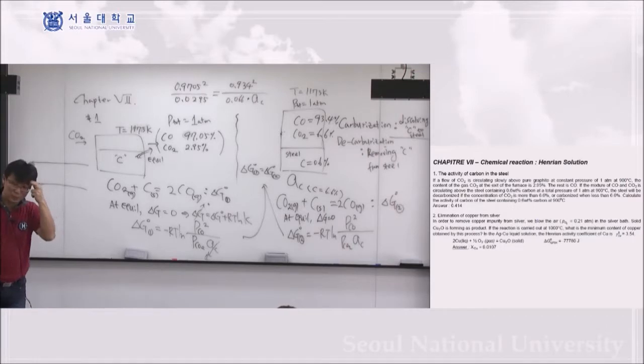The most famous use of this kind of technique is the blade. If you have a blade, typically one side is very ductile and the other side is very, very hard. When you have a knife, the edge you use to cut is very hard, but it's not ductile, so you can really cut your material, your food. But the other side, which we call the shoulder side, should be ductile. If the entire thing were very brittle and you accidentally dropped the knife, it would just break down, and then you could not use your knife.